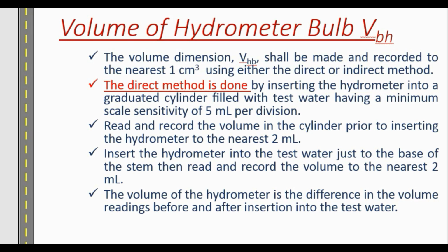Then insert the hydrometer in the water. There will be a rise in water due to insertion of the hydrometer. This rise in the water is the volume of the hydrometer bulb. We will note this volume, which will be used in our calculation.